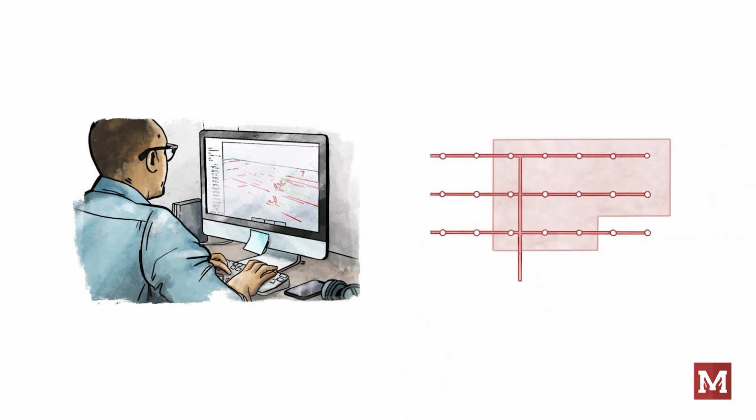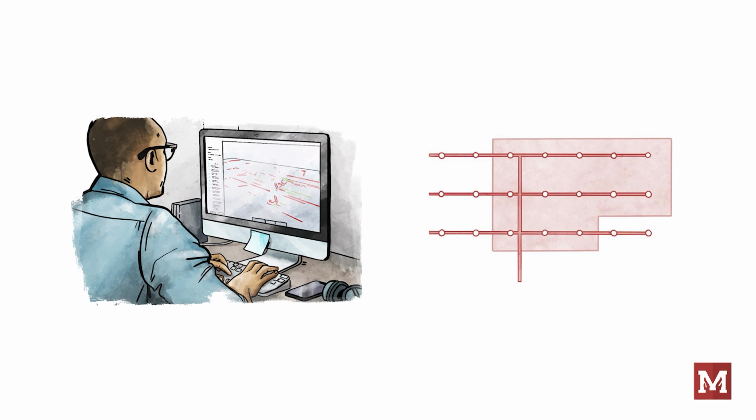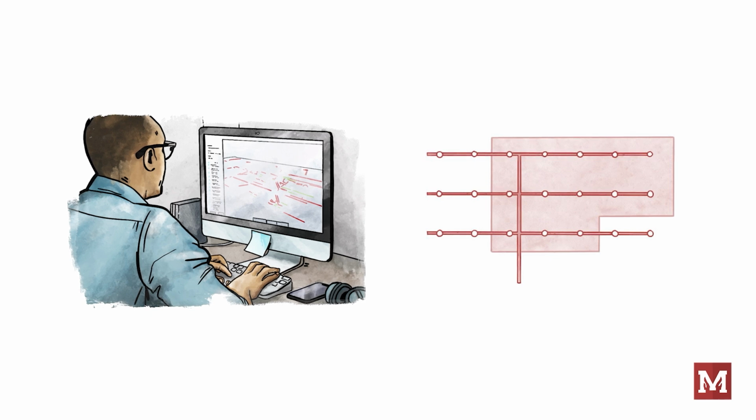The fire protection designer of record is responsible to calculate the hydraulically most demanding area of the building. This represents the highest water and pressure requirement of the building. This is often the furthest point from the sprinkler riser, but can also be closer to the riser if pipe sizing or other factors influence the hydraulic performance.